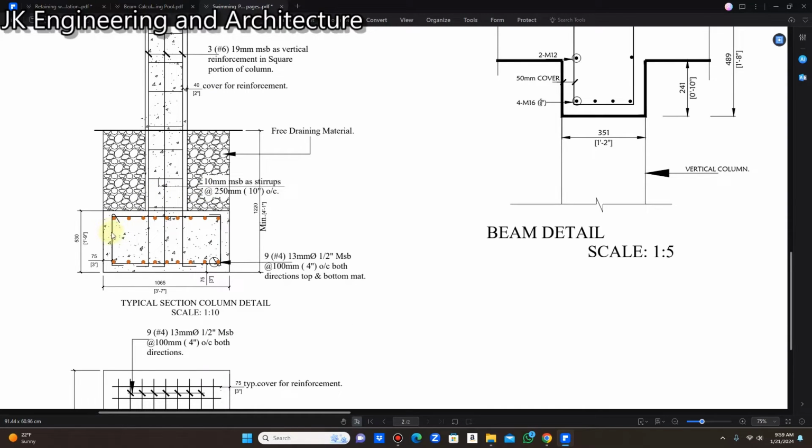And here I have these hook bars at the end. These hook bars are used for earthquake purposes, since the footing carries a double mat. In the event that we have any seismic action, any earthquake, the top mat and the bottom mat move in unison and they don't break away from each other.